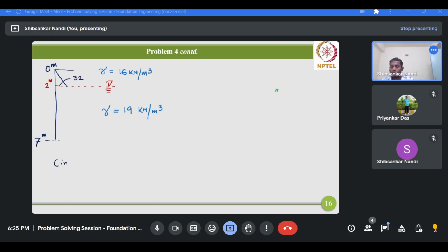This diagram is given in kPa. Once it encounters the water table, you have to consider the pore water pressure also. You calculate total stress, calculate pore water pressure, then subtract the pore water pressure from the total stress to get the effective stress at that level.